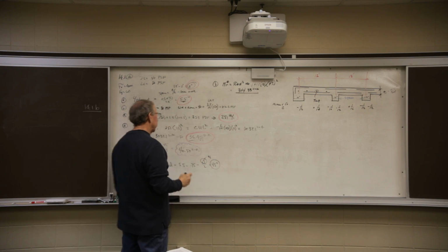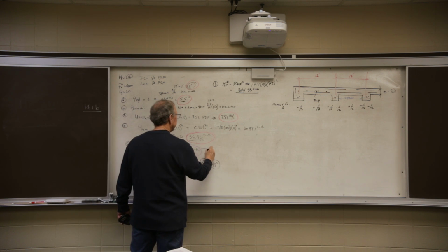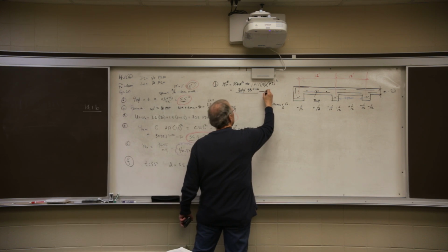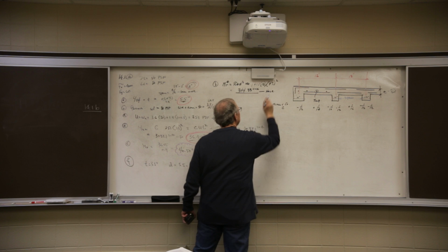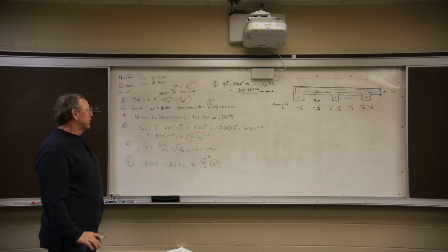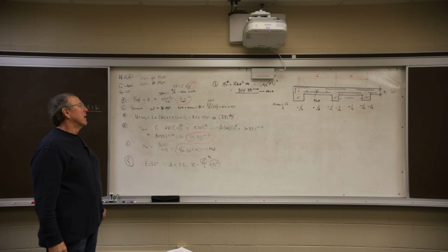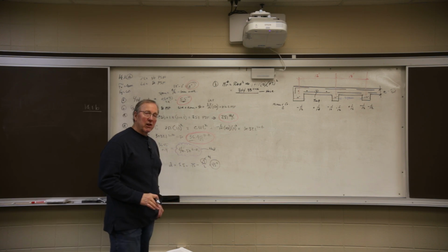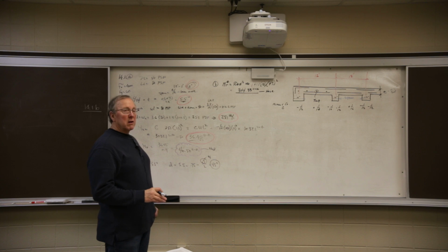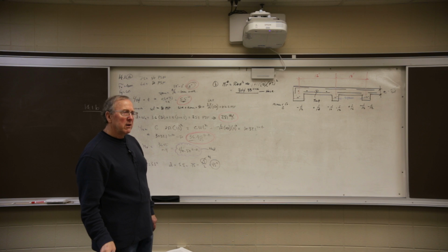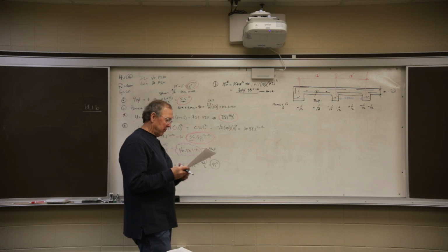Okay, this is what I need. This is what that particular cross-section can provide. I need 40.5 inch kips of resistance. I have 344 inch kips of resistance. What does that tell me? It tells me it's got a section that has plenty of depth to take care of flexure. So flexure's out of our life now. We've checked it and made sure the bending was okay.